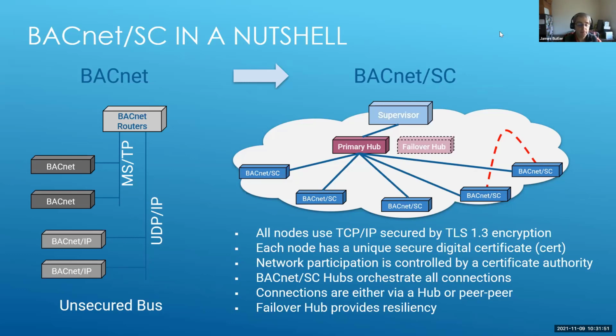BACnet Secure Connect and BACnet IP are similar in that they both use IP networks. But we think that Secure Connect will be preferred by cybersecurity-conscious customers in the future because it is based on state-of-the-art IT cybersecurity.